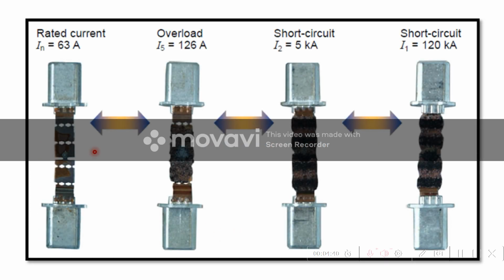And this is how a fuse looks like, a normal rated fuse. And here this area will be enclosed inside a fuse porcelain casing, and these are the internal elements in the fuse connected by small links. For the normal current rating of 63 ampere, the normal current flows from top to bottom. If the current exceeds the normal level of 63 ampere, we call it overload. On overload, here it is double the current rating of the fuse, a partial melting happens in the middle, in the elements.